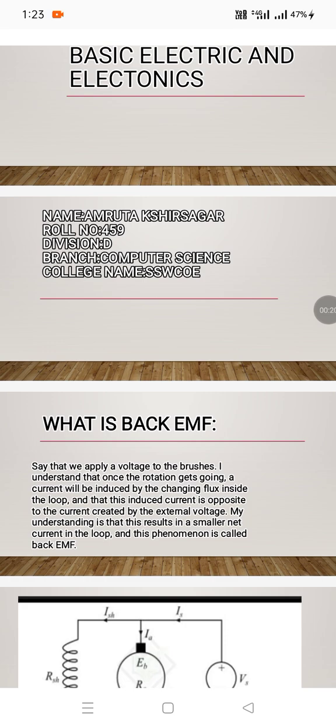When the motor armature rotates, the conductors also rotate and hence cut the flux produced by the field windings. Hence, according to Faraday's law of electromagnetic induction, EMF is induced in them, whose direction is found using Fleming's right hand rule. It is found that this induced EMF in the armature is opposite to the supply voltage, so it is called back EMF or counter EMF. EB is the symbol denoted for the back EMF.